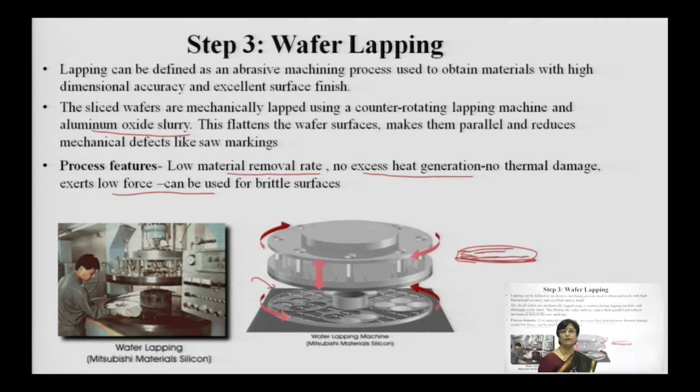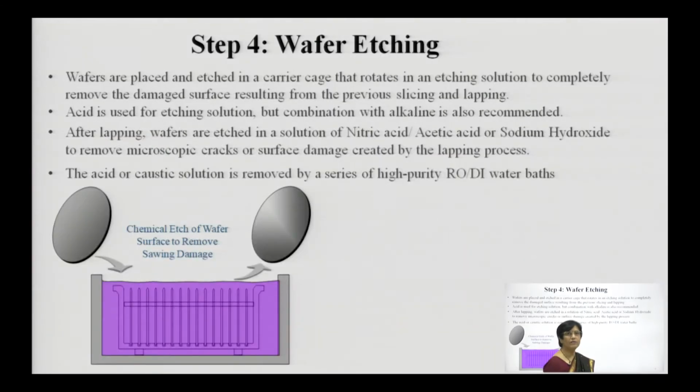Okay, once we have done lapping, we are going ahead with the next step. You have a lot of material available on the silicon, and you need to clean it. To clean it before going for polishing, we don't want any contamination on the wafer, and therefore we go for etching. Now this etching is a very limited period etching, because you don't want the wafer to come in contact with chemicals at high temperature or for longer duration.